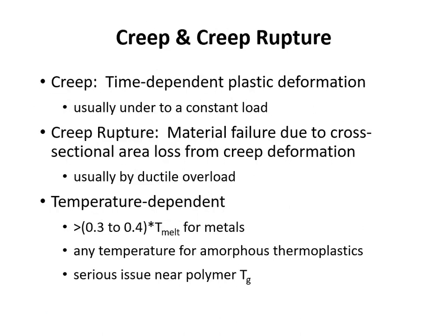Okay, kind of moving to the opposite end of the spectrum, getting away from brittle failure. And again, fatigue is definitely a bit of an extension of brittle failure in that it just provides a cyclic loading means of increasing our a, our crack length, to the point where we exceed K1C. Now we're going to shift back to something that is definitely in the realm of ductile failure, and this is creep and creep rupture.